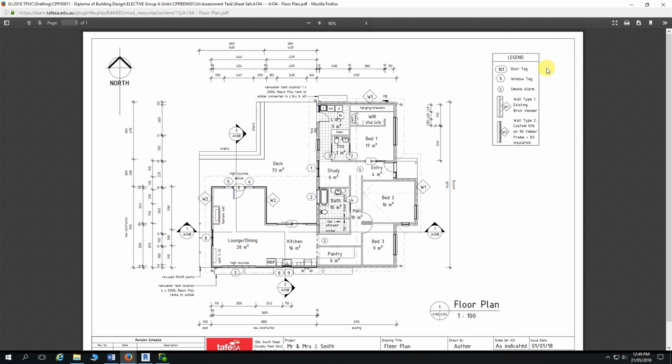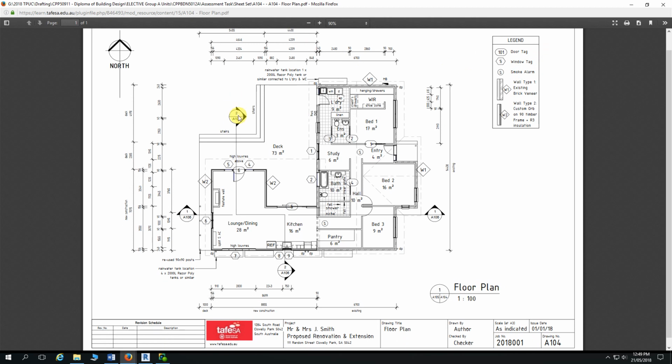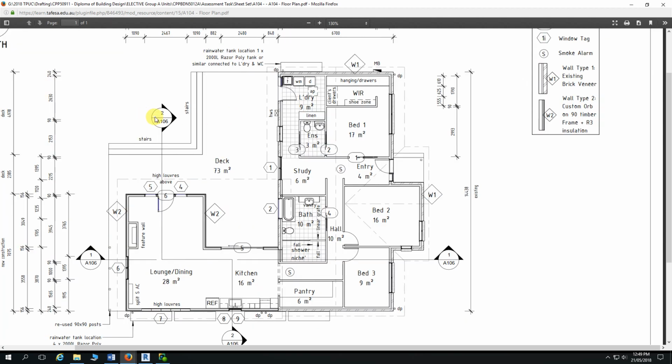The section markings in the sections themselves, when do you want those putting in? We've got nothing in there at the moment. The actual number, the section number and the A106, the A106 refers to the sheet that the section views go onto. Because we haven't put the section views onto a sheet yet, in fact we haven't worked on them yet, it's not until the views go onto a sheet that these numbers will appear in the section heads. So that's an automatic thing. So that's to come. Thanks.